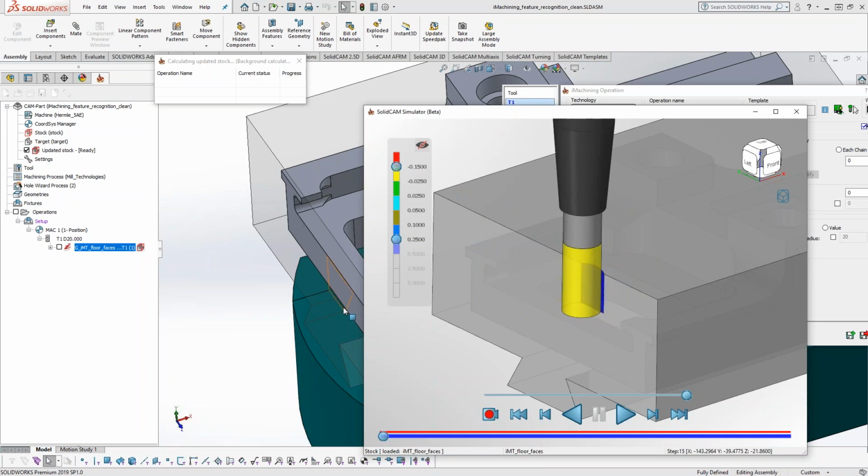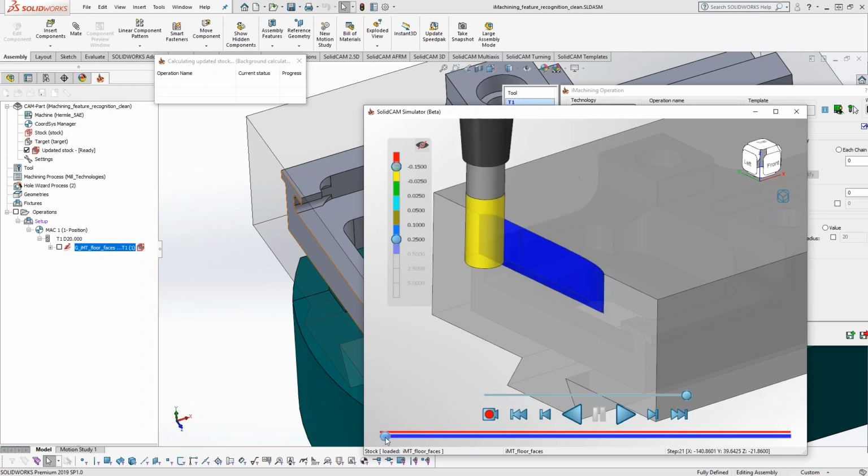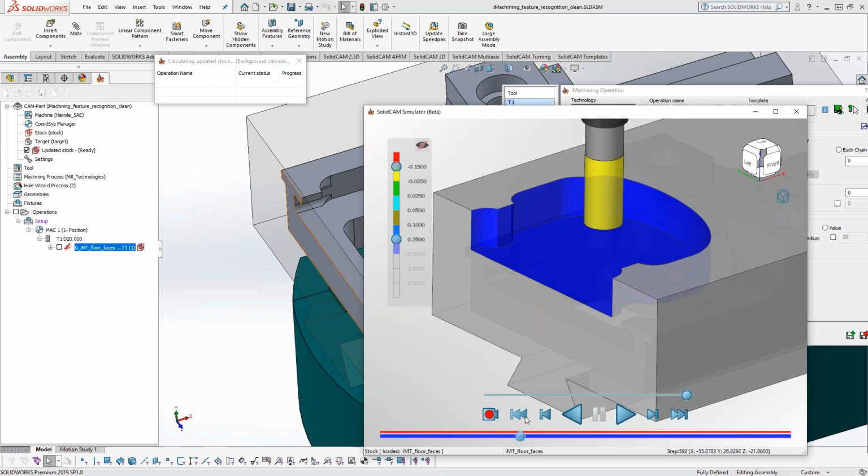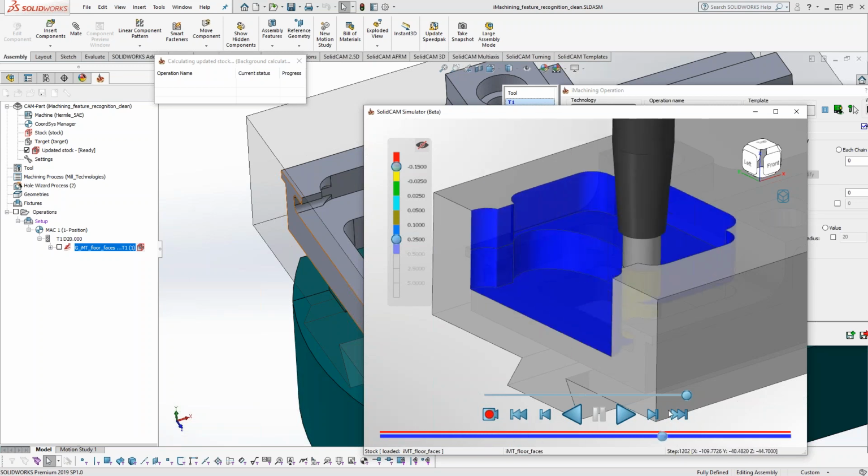So once again, we automatically extend the geometry to the stock, so that way we're plunging out in air and you don't have to do sketching. You can see here, by coming to the beginning of the toolpath, that it's entering correctly from the outside of the material right through.